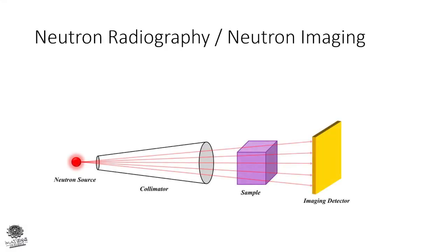Neutron radiography. In this method, a specimen is irradiated with neutrons and an image is formed based on difference in neutron scattering. Light elements such as hydrogen interact strongly with neutrons. Consequently, materials like water, oil, and many polymers are highly visible within otherwise neutron transparent metals.